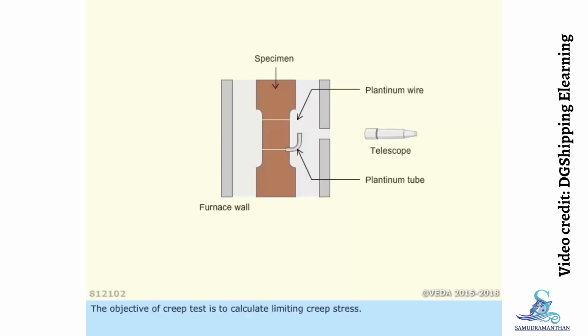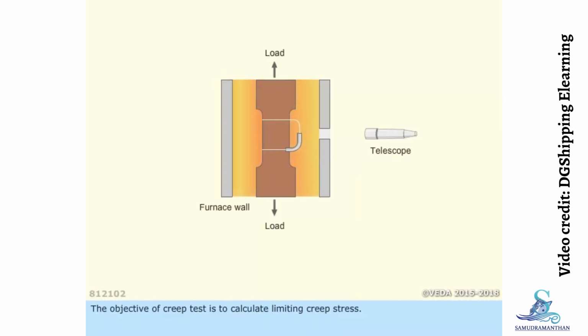The objective of creep test is to calculate limiting creep stress. This test measures and records stress, strain, temperature, and time. The creep test consists of applying a fixed load to a test piece and maintaining it at a uniform temperature.